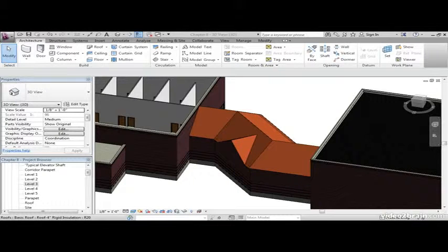The deal is we need to actually edit the footprint of the roof. Then we need to split the area of the roof that has become the dormer. We add a couple of slope barriers and we have a dormer. But actually, the first thing we're going to have to do is fix the third floor floor plan and introduce a new topic called view range.